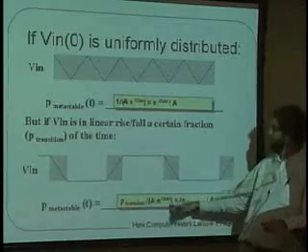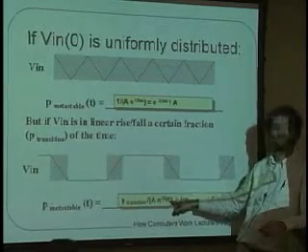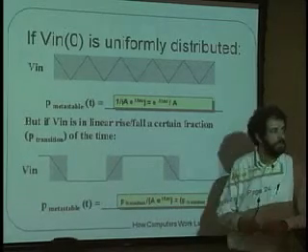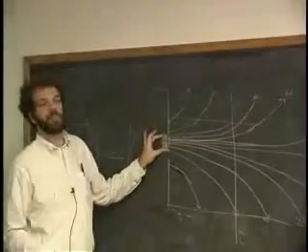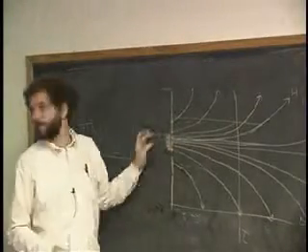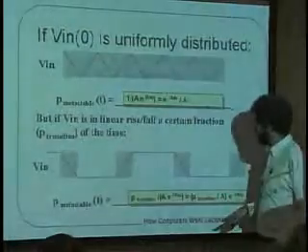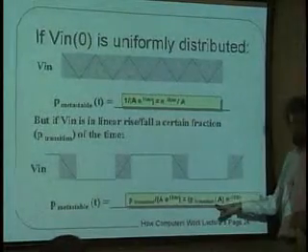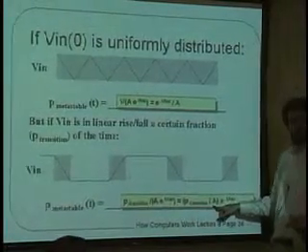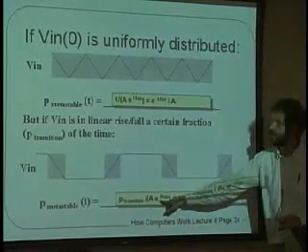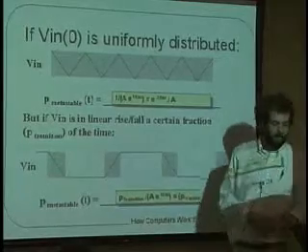And then you also have this a e to the t over tau, which has to do with what the probability is based on exactly how big this part of the curve is. Okay? And so, in summary, what you get is the probability that you are metastable is p transition divided by this amplification A of the feedback times e to the minus t over tau, because it's on the bottom over here. So e to the minus t over tau.